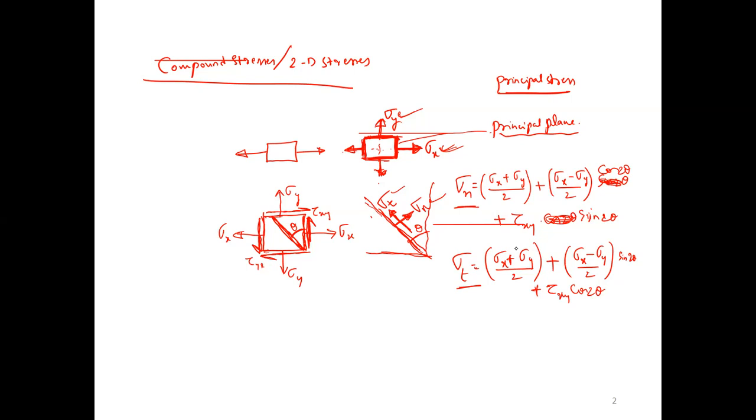Next, I will explain how to compute the major principal stress and minor principal stress. We are getting principal planes. Principal plane is for a two-dimensional shear stress as well as axial stress system. We have normal stress and tangential stress on the plane, but with respect to the element, we get two stresses, the major principal stress and the minor principal stress.